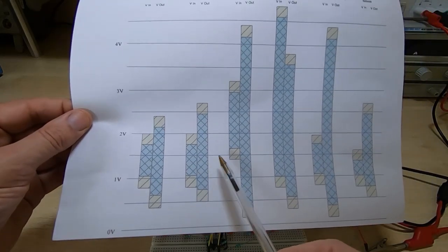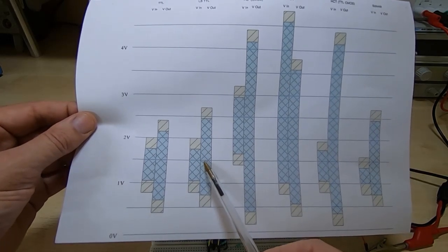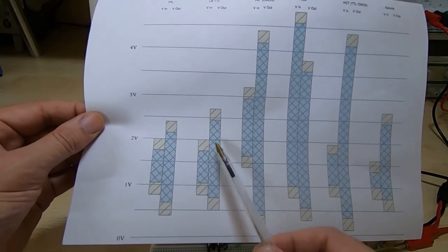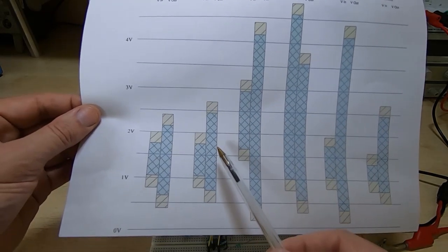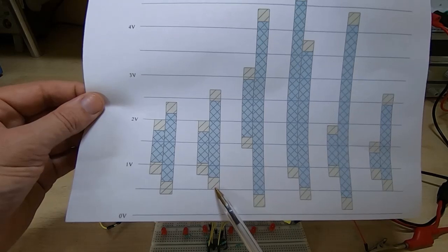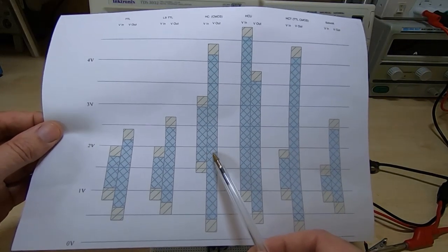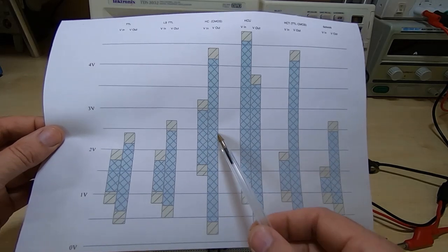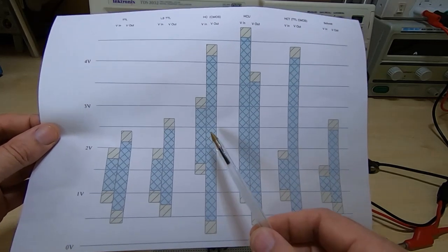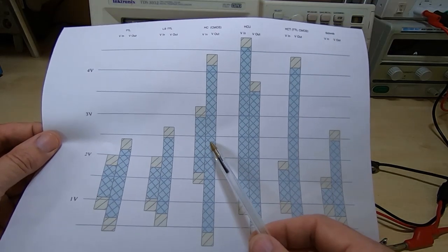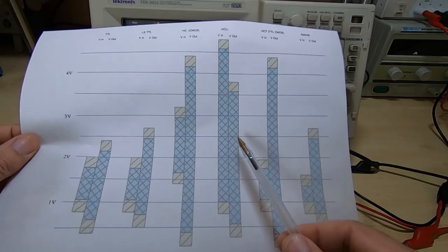And you can see that for each different type, so the next one's an LS, so 74 LS series, quite similar, but has a slightly higher output voltage in the high mode and a slightly higher output voltage in the low mode. Then we go on to the HC, so these are 74 HCs. These are the ones that most often cause problems when they're mixed and matched with standard 74 LS or the standard 74 series devices.